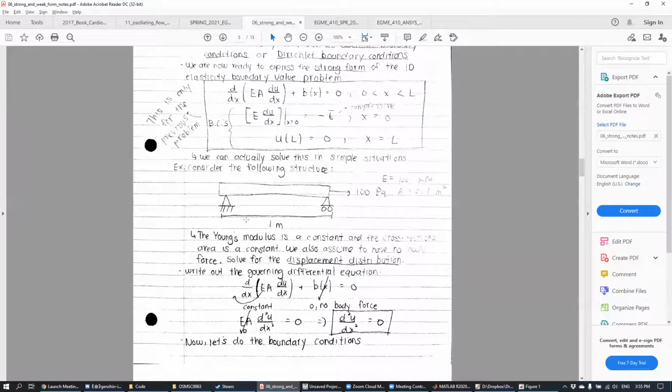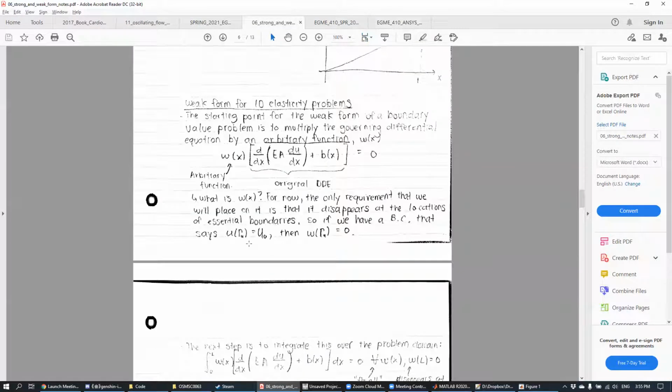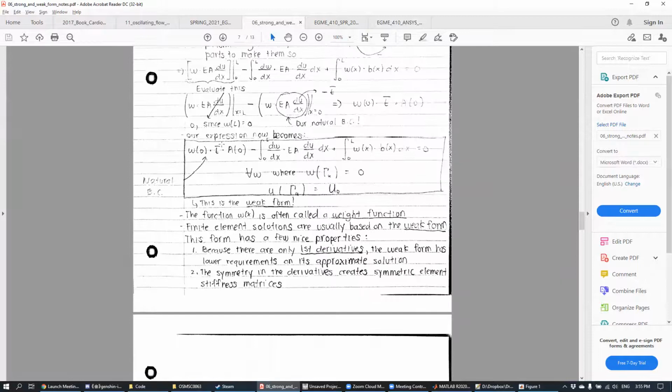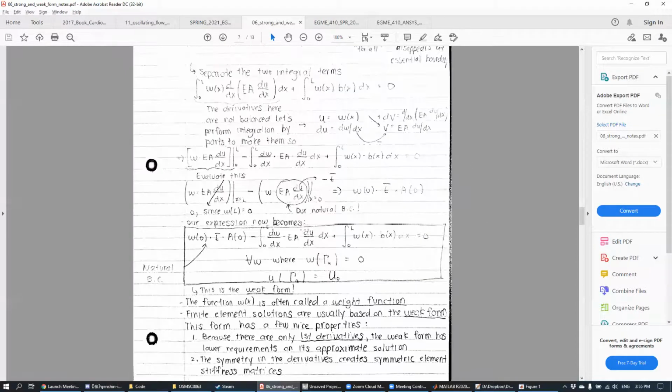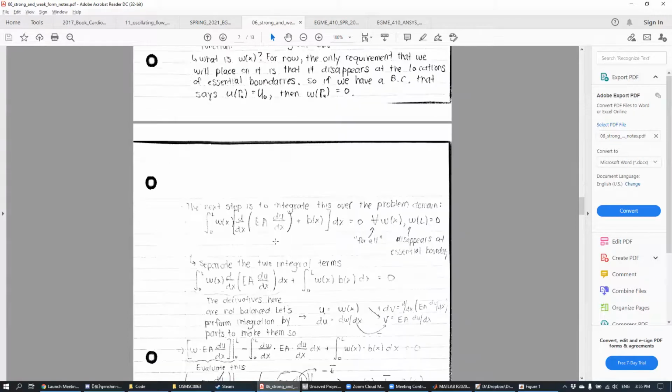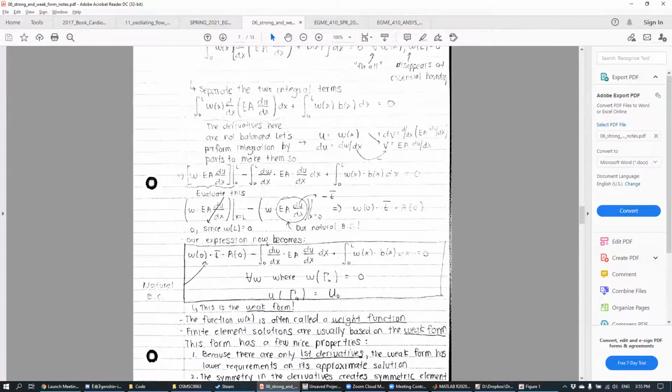So actually I just had it open. I was writing your guys' again earlier. And so you're talking about this term right here, right? Yeah, exactly. For the traction boundary condition, what these represent is we're evaluating both the weighting function and the area function at the same location as the traction boundary. In this derivation, I did the case where our traction boundary condition was at x equal to 0, so I evaluated these at x equal to 0. But if the traction boundary condition was at the other side, then we would evaluate these at x equal to L, for the A.